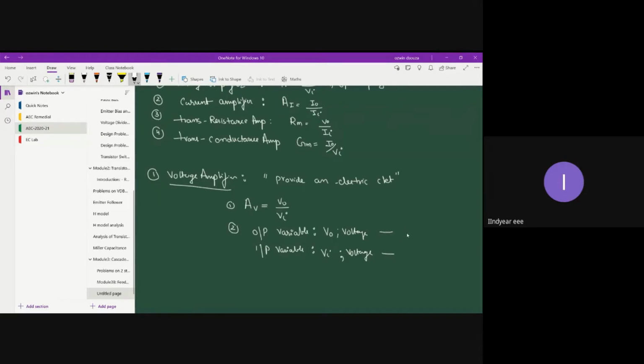On the other hand, if your signal were to be the current, then you can go for Norton's equivalent circuit. Since it is voltage, for both the circuits, that is for the input circuit as well as the output circuit, we use Thevenin's theorem. So this is the algorithm.